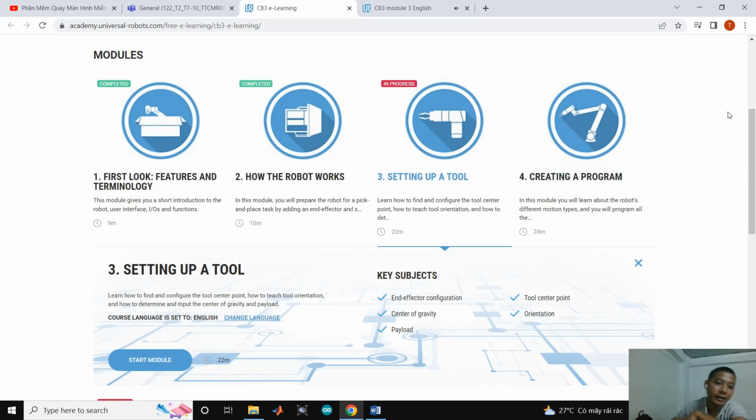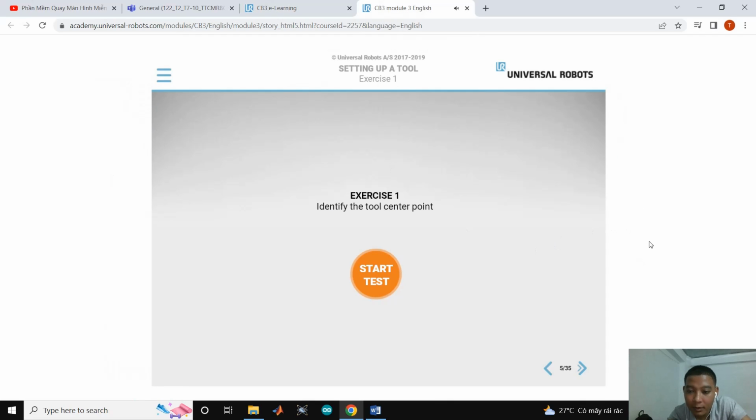Ở slide thứ tư này thì theo những gì mình nghe được thì center point được định cấu hình trong mục TCP. Điểm trung tâm của công cụ có thể được xác định bằng cách tìm điểm tiếp xúc giữa công cụ và chi tiết gia công. TCP nằm ở trung tâm giữa các điểm tiếp xúc giữa công cụ và chi tiết gia công. Qua slide thứ năm thì sẽ là về ví dụ để tìm center point.